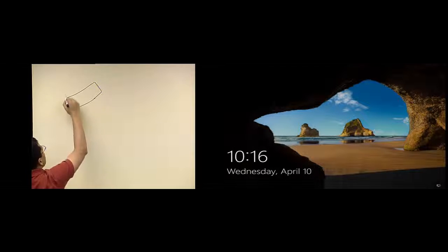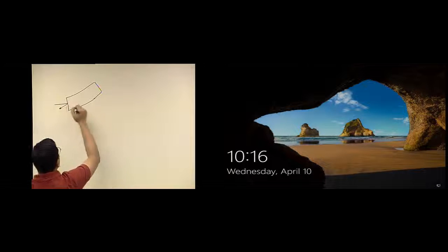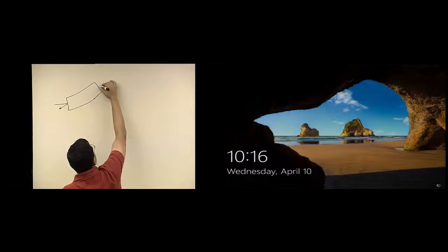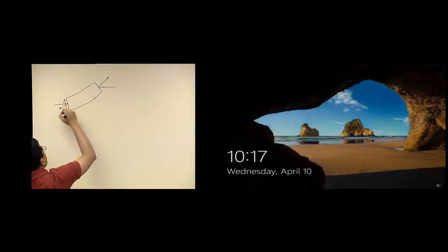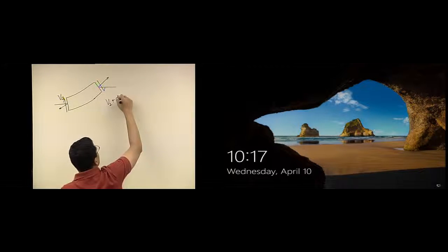So the plane sections remain plane. Plane sections remain perpendicular to the reference line. Right, so this is the horizontal axis, this is the normal to the plane. Okay, so we have a shear force here, that's V2. We have a shear force here, that's V2 plus dV2 over dx1 times dx1.